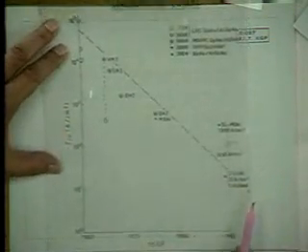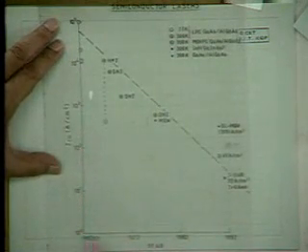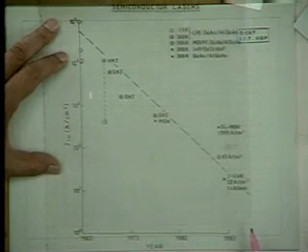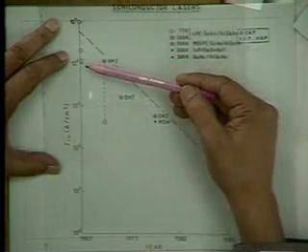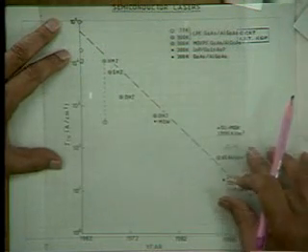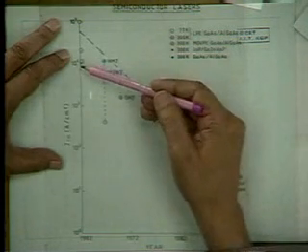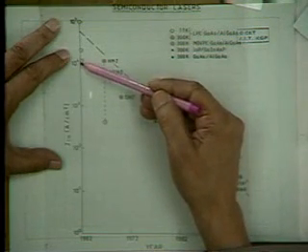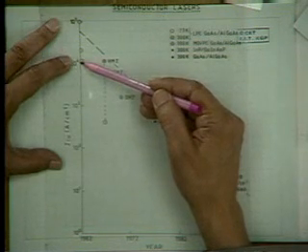This is a plot of the threshold current of lasers in the last 30 years, and we'll see how over this period of time, lasers, which were very novel and rather laboratory curiosities, had currents of the order of 10 to the power 4, 10,000 amperes per centimeter squared or more.